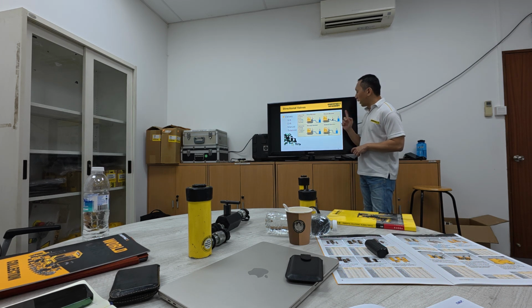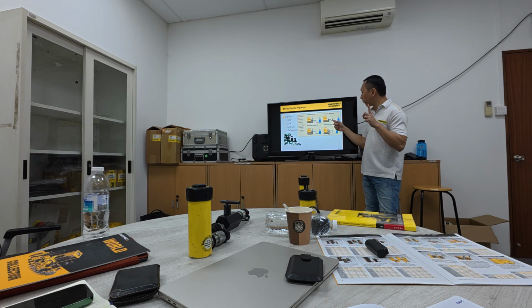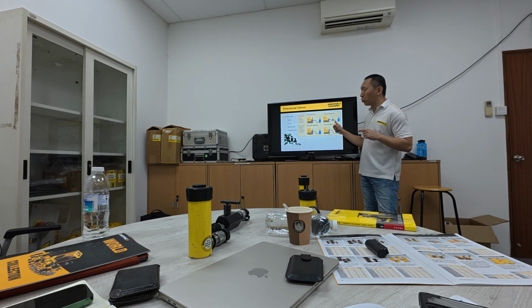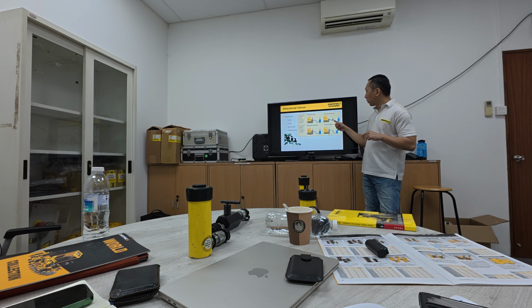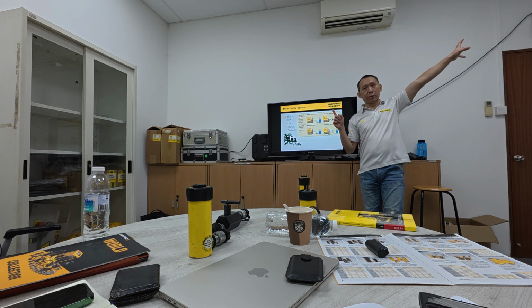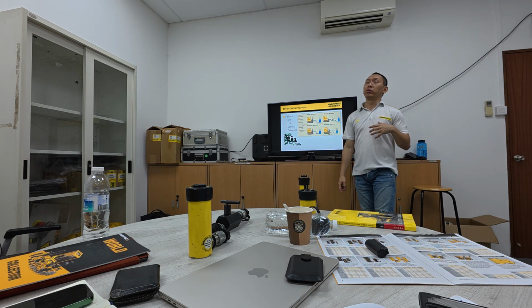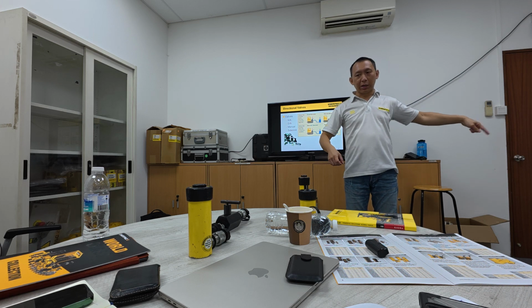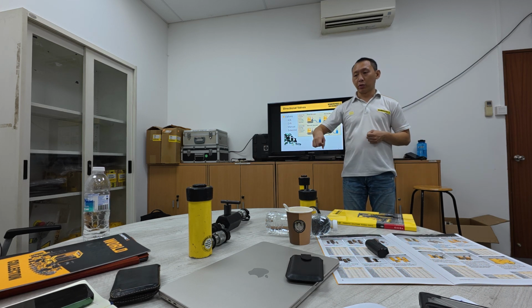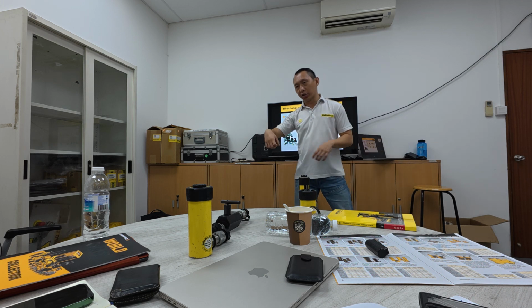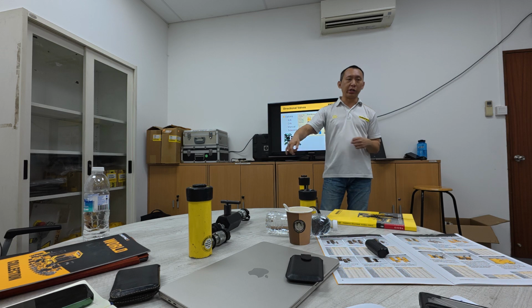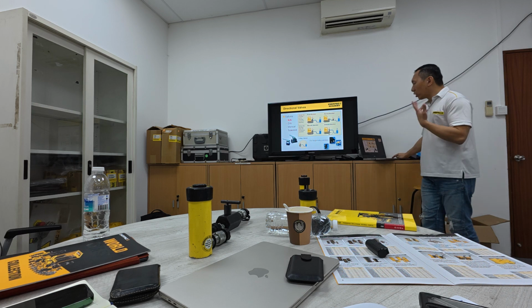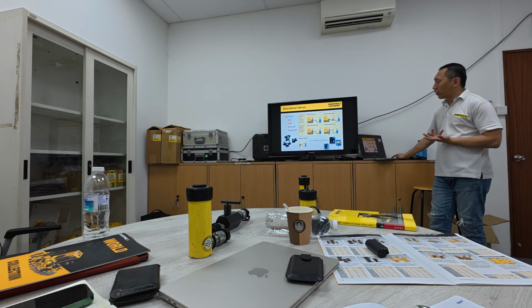Just now I mentioned the remote valve. You see, this valve is outside the pump. This is a pump-mounted valve, and this is a remote valve. It means the hose from the pump connects to this remote valve, which can be put somewhere else. For example, in a production line you just see the valve there, but the pump is somewhere else, because one pump will cater to multiple valves. At this station they need to clamp, the next station they need to release, so they can use the remote valve to configure a production line. So take note: 3-way valve for single acting, 4-way valve for double acting.